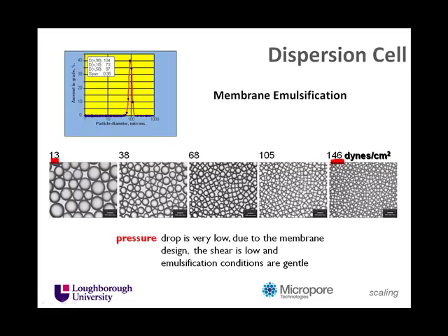So instead of looking at it visually, if we looked at it down a laser diffraction system, a Malvern as it happens, we can see here the D50 of 87 microns with a span of 0.36. So they're not absolutely monosized spheres, but they are very uniform spheres.